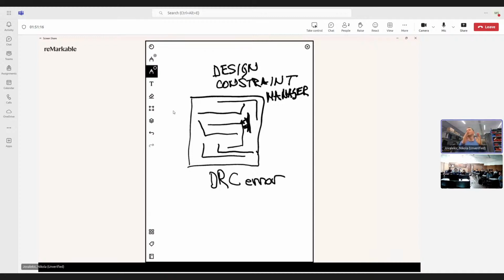And you will see the minimum clearance track to track is, I don't know, like 0.15 millimeters. Then you will see the minimum via hole, when we are talking about via. This is the hole, and this is called the annular ring. They will say, okay, we can produce a minimum of 0.2 millimeter hole. Then you will set up via for your design minimum 0.2, and this should be, for example, 0.5 millimeter minimum. All these things you will find on the website of the PCB manufacturer, and you really need to understand that and put all that in your rules.